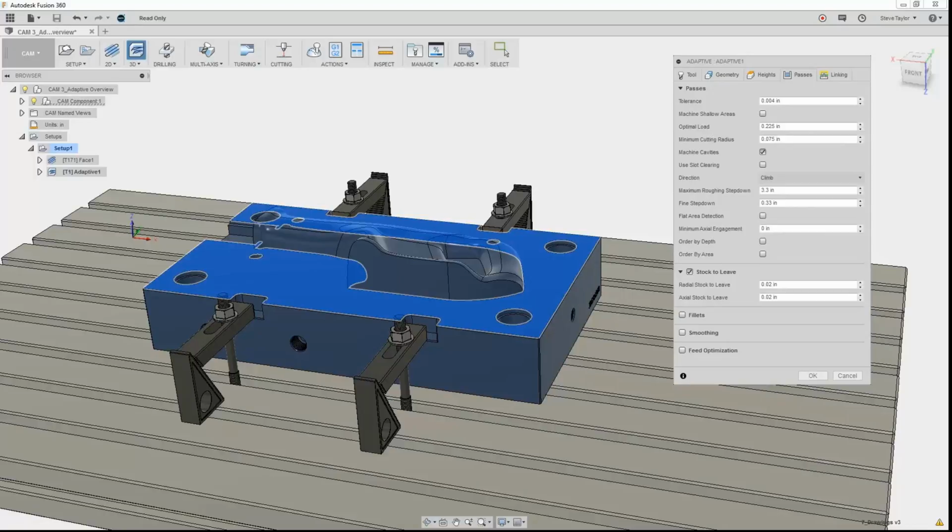Plus, by using the parametrics, it also means if we change the tool to a different length, it will automatically update to 80% of the new length for the maximum step down for that particular tool. So by actually not putting in the value there, but using the parametrics to calculate the value, it means that if you change the tooling, it will automatically update.